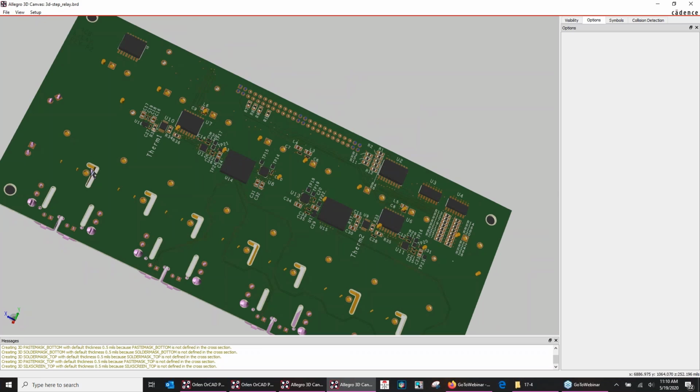What you're seeing here is air holes, air slots being cut in here. And this pin was high speed, and it's a high voltage pin. And to pass UL and use FR4 material, we had to cut air slots in here so the voltage didn't creep across here past the HiPot test in the UL testing that we did. So that was one of the problems.